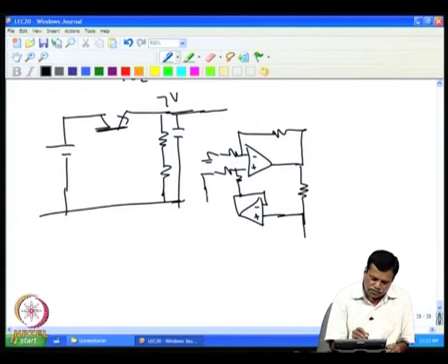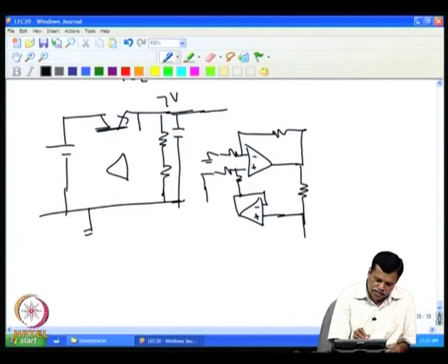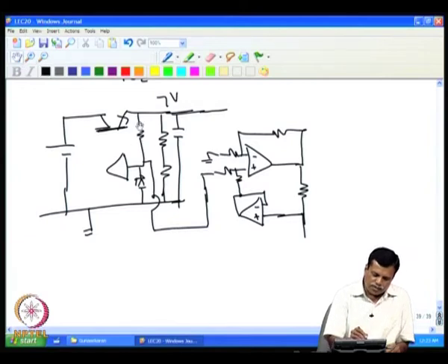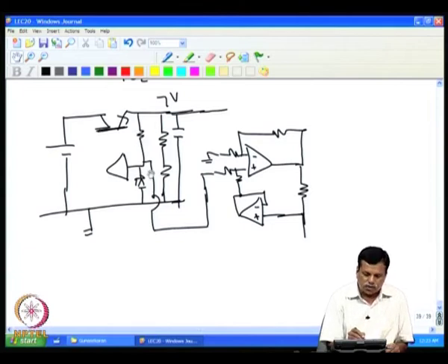And this is supposed to be given to V reference, and we have here the V reference, this is grounded, and in the regulator we have on V reference 2.5 volt. The same 2.5 volt can be utilized if the current drawn is small. If more current is required, one can readjust this resistance, because if you need more current through this, then in that case we have to reduce this resistance to supply the required amount of current to this, but normally this resistance can be kept high, so that this current is negligible. So, one can have a current source like this.